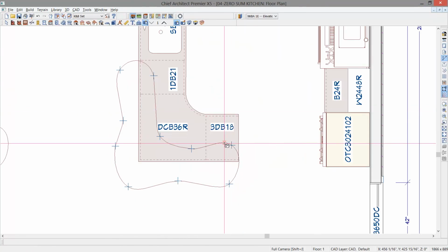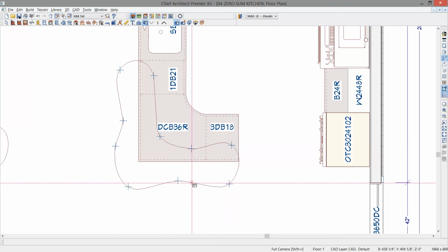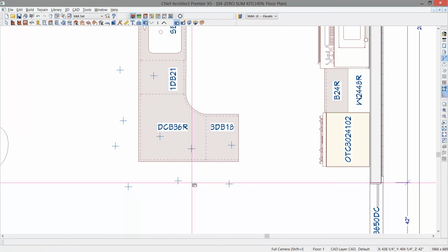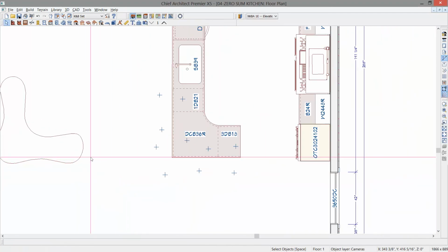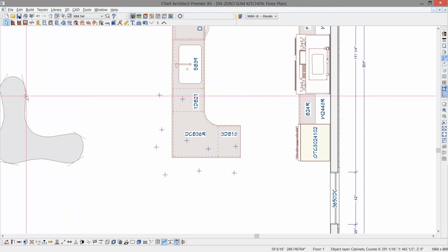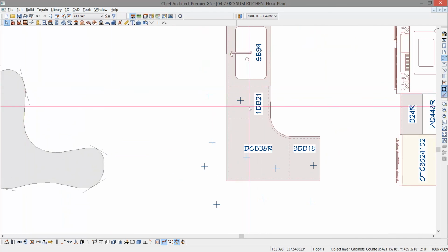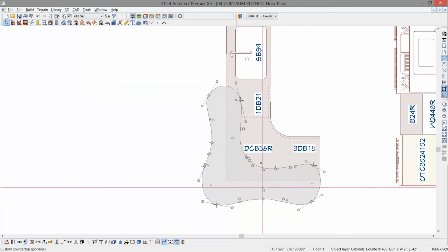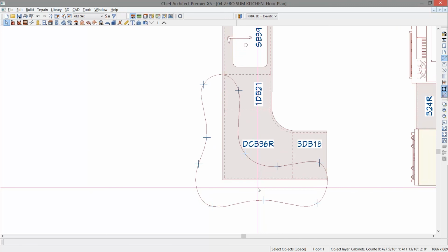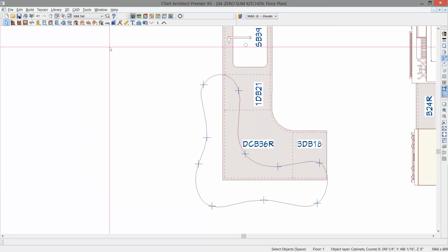The next step is I'm going to go ahead and delete that countertop that isn't quite perfect, and we'll move in the other countertop that has the exact dimensions. I'm just going to use a point-to-point move, and we'll just snap that over here. Now the next step to support this countertop is to use standoffs. And a standoff is another CAD tool that we'll use.